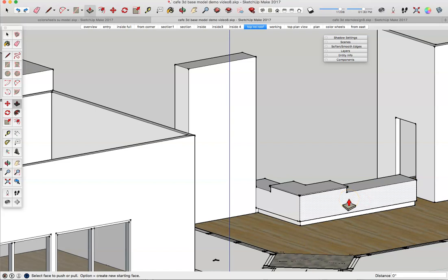Okay, so now, and you may say, oh, Mr. Stern, I have a lot of curves in my design. And this is the difficulty, is you're going to have to use a lot more different tools. If you have a complex profile like this, you're actually going to have to sweep it along a path. It's a tool that I don't like very much. So if you have curved shapes, I just keep them simple. I wouldn't get into these little refinements. There's just not the time to do it, unfortunately.